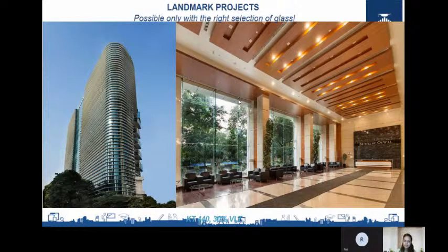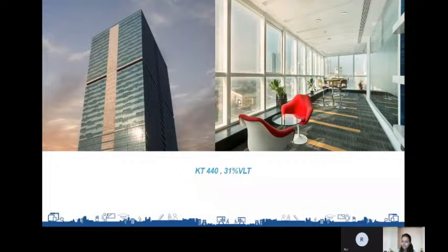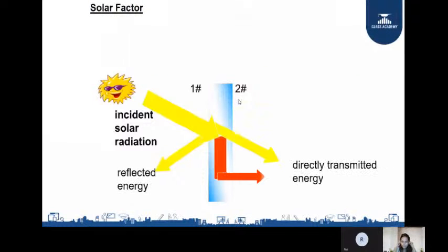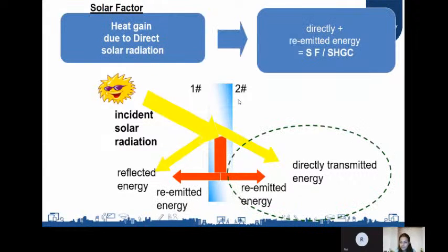Okay, so this was about fire rated glass. Now we have the protective glasses. There are basically three types of glass: attack resistant, bullet resistant, and blast resistant security glasses. In attack resistant, this will give you protection from vandalism and theft. Generally, people use it for shop fronts and premium showrooms where there is a possibility of theft, and also for high-end residences, high-end villas or farmhouses.